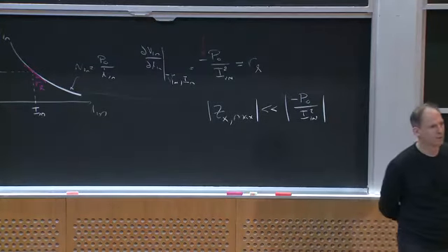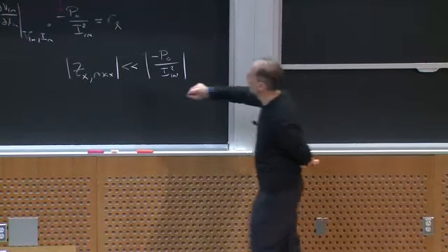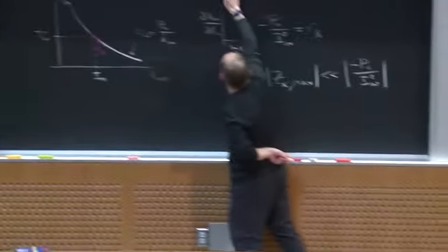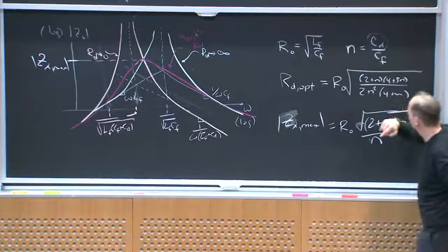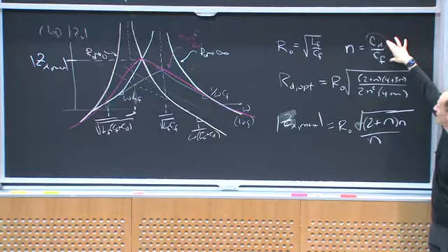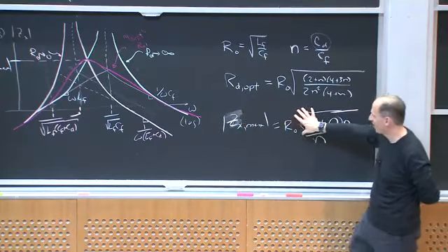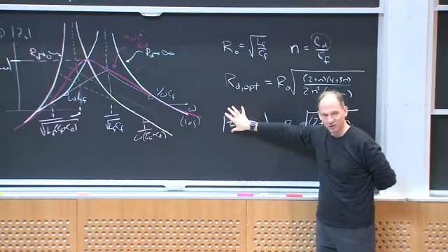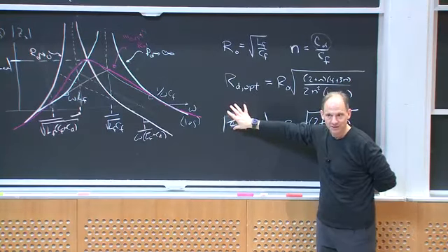So I've got to pick my damping, and if I were to use this capacitive damping scheme, that's going to drive me to pick some minimum value of the damping capacitance so that I can minimize the maximum value of my filter output impedance across frequency. Does that make sense to everybody?